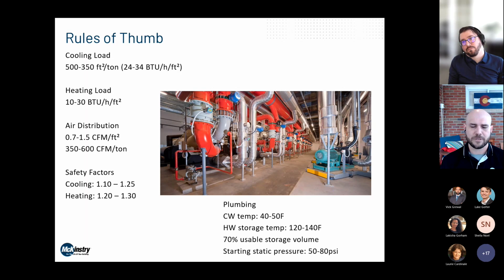There's certainly concern about Legionella, a bacteria that grows in warm storage tanks that are particularly exposed to oxygen. But above 140, that's killed off. So, any domestic hot water storage tank, only about 70% of its volume is considered usable. After that, it tends to be too diluted, and the water isn't warm anymore.